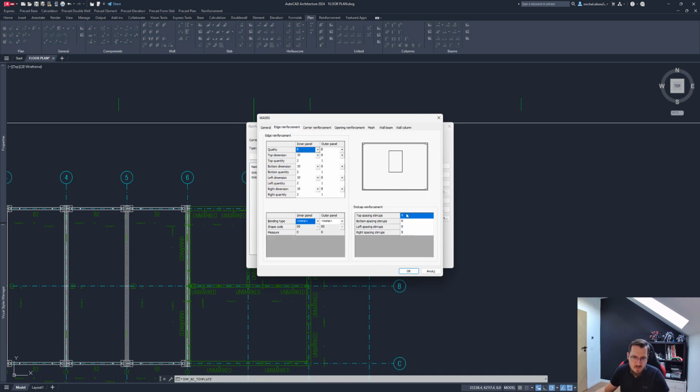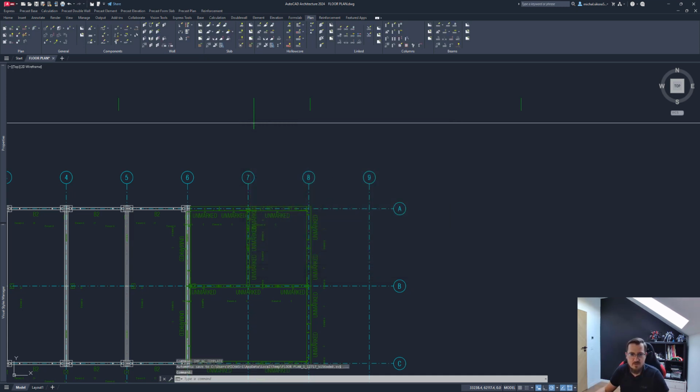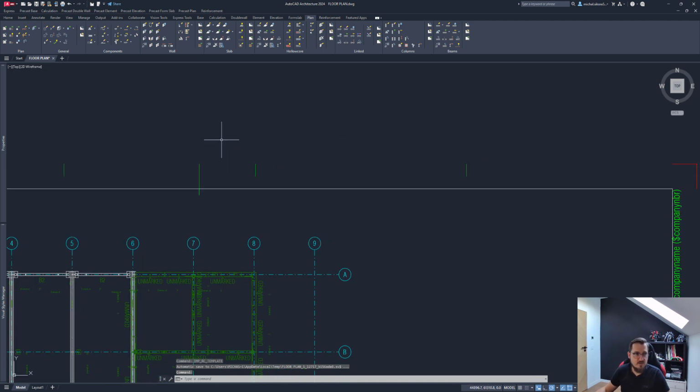In the edge reinforcement, we can specify the spacing for the end cap reinforcement if it is specified for a particular type of end cap. So let's do that now. In Impact for AutoCAD, you don't really immediately see the results of your settings for like reinforcement. That only happens once you create the drawings. But that is pretty easy to set up, and then very easy to verify that all is good once you have the elements all specified and all the settings specified.